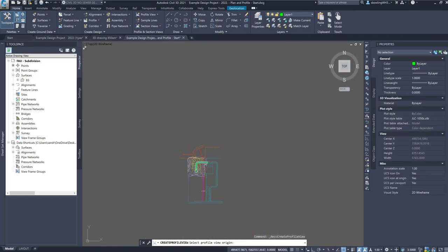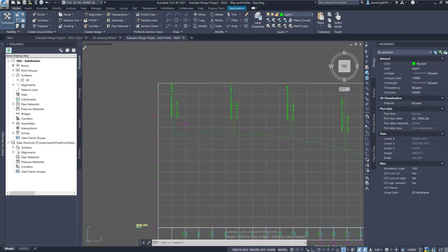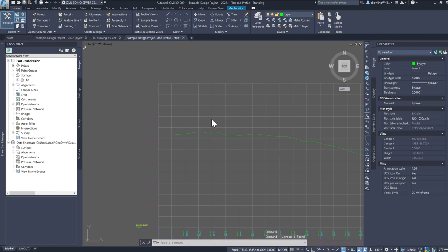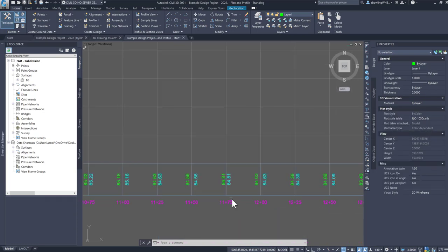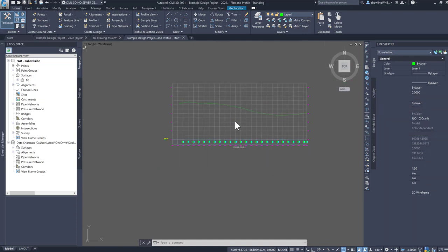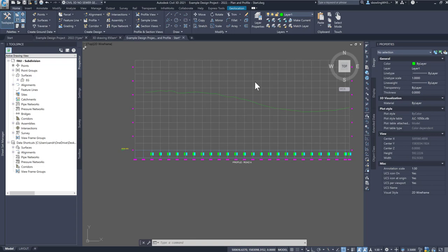I'm going to come over here and just set a point here. This is our profile of our ground. Now I'm going to delete these labels. I don't need these on this one. Typically you do not label the ground elevations like this for the existing grade. We'll come back and update these elevations. Notice that they're the same numbers. Once we create the proposed profile, then we will update these. All right, so that is our existing profile. I'm going to stop here, and then I'm going to show you how to draw a proposed profile.